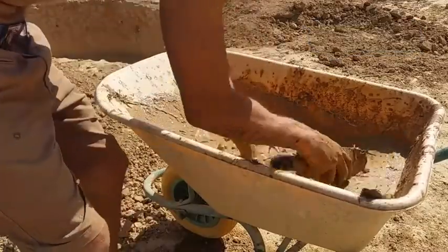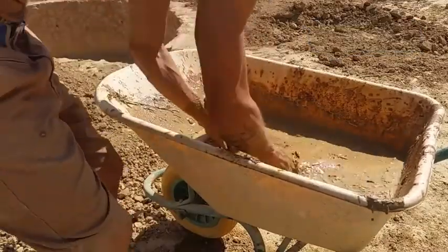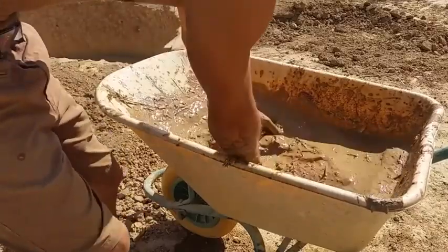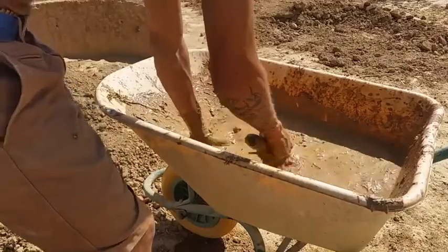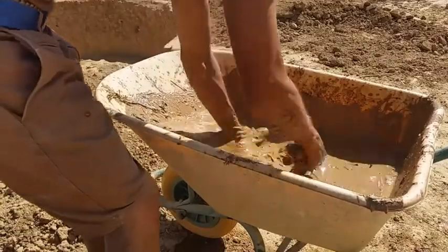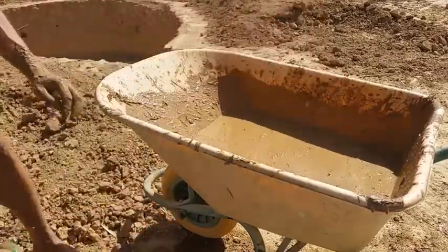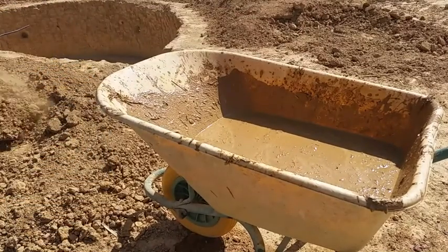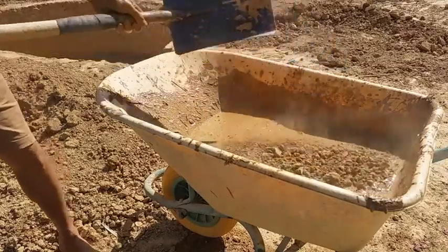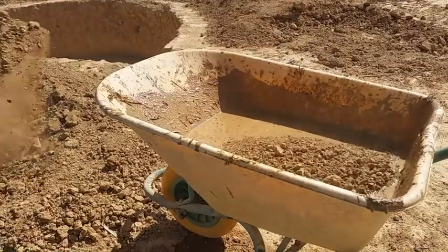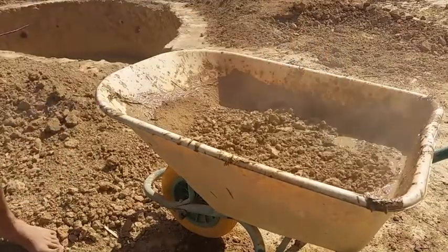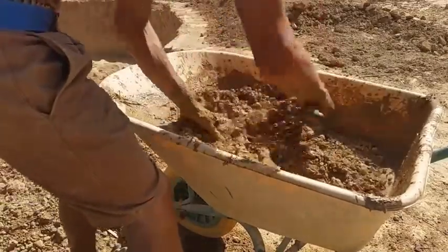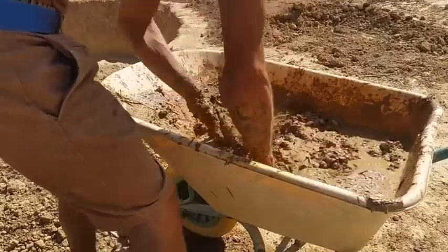Heavy rain or water presence may easily destroy mud structures. The material does not have a high tensile strength, which means it may collapse if there's a lot of applied weight. Mud is also not fireproof or pest-proof. It cannot withstand fire, which is a hazard, and it can also be possibly infested by termites or small rodents. Mud structures also require regular maintenance, and due to the nature of the material, limits its capabilities for design.